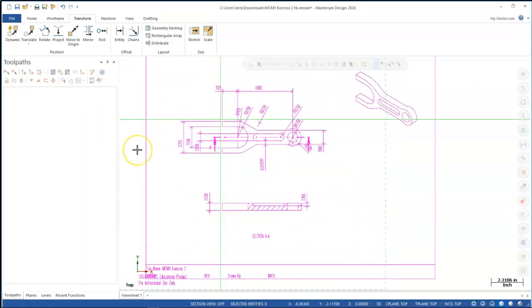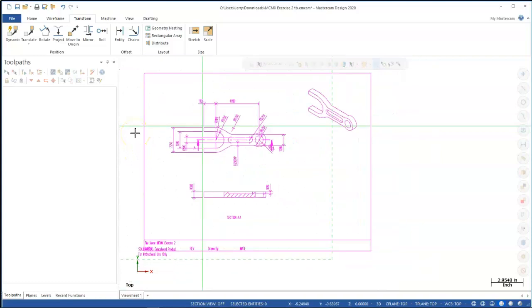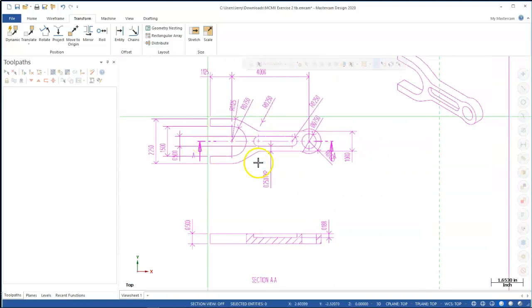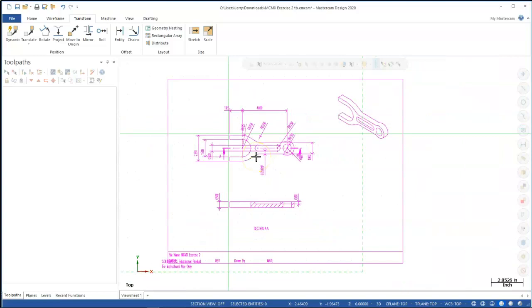And pretty much when I ran through this, checking out the DWG earlier, I managed to not scale the title block, and then when I moved parts, all the dimensions moved away, and it looked really weird. So let's do all of our manipulations before, and then I wouldn't have to do those undos to get it back to this point. But I'm happy with the results here. Do I really need all of the title block and geometry? Not particularly. I could just go ahead and erase it. If it's handy to have it in the background, we go ahead and leave it.